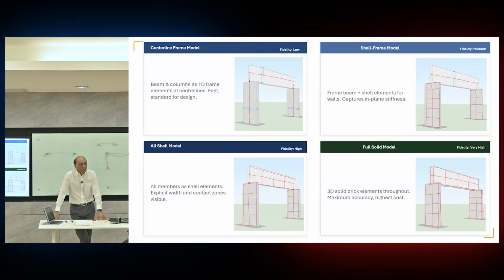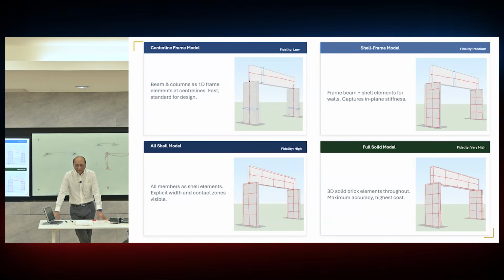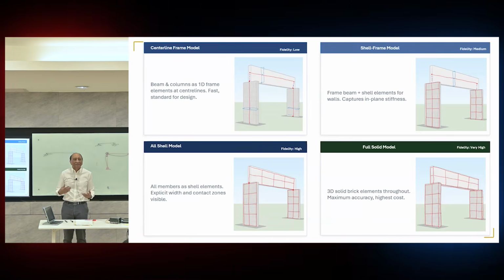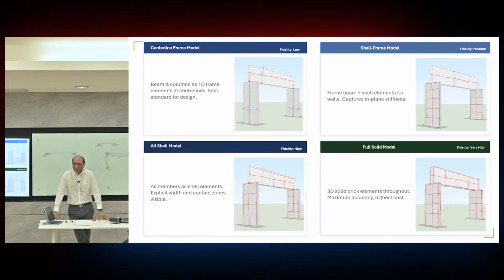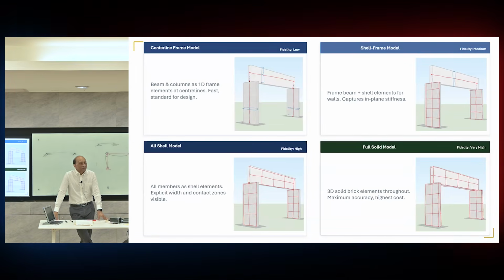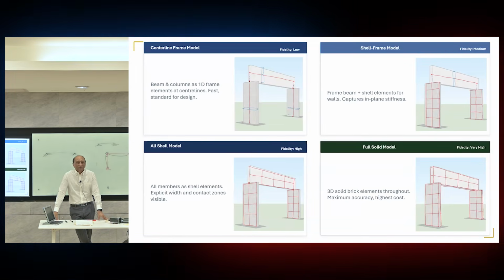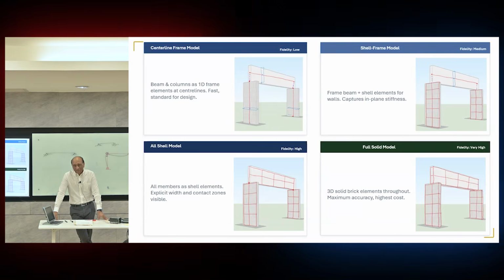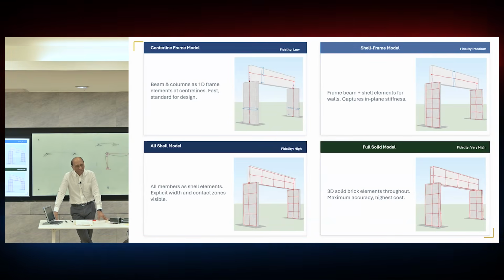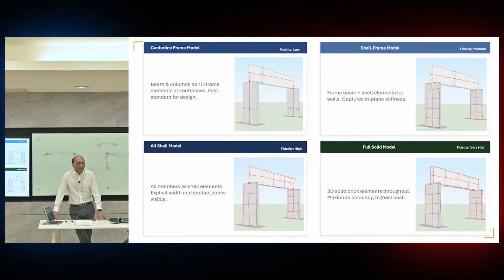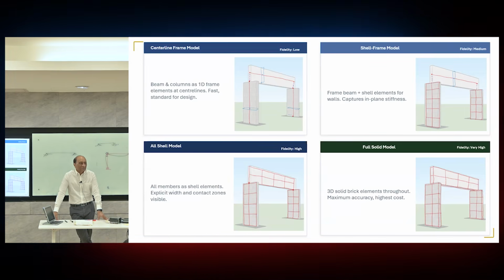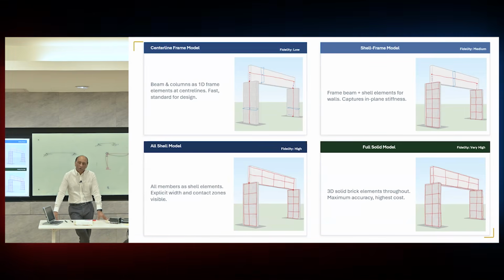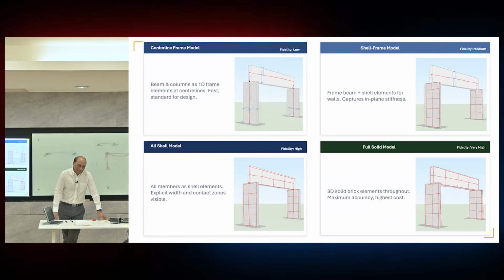Now you don't need to create any artificial things. But the problem is now you will not get any bending moment in the beam because shell elements will not give you any bending moment. Shell elements only give you stresses. They don't have in-plane bending moment. So that means then to calculate the bending moment to design, you will have to do some kind of integration from the shell results. So you solve one problem, but now you create another problem.